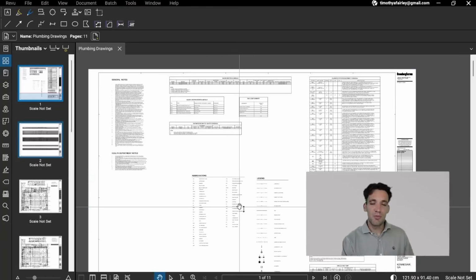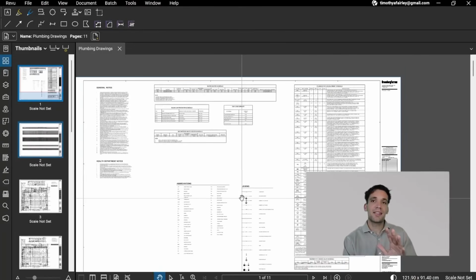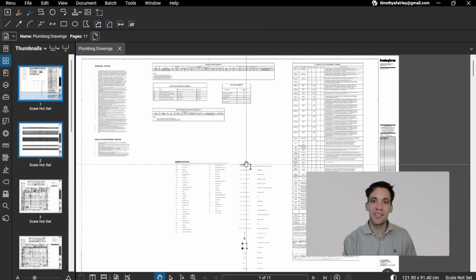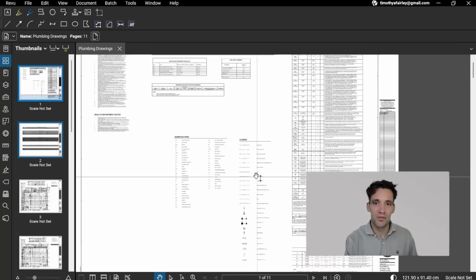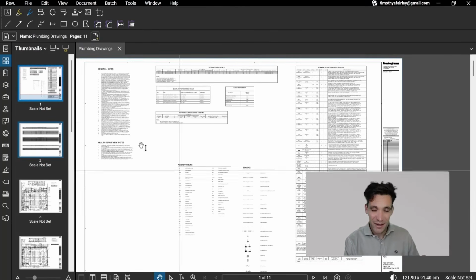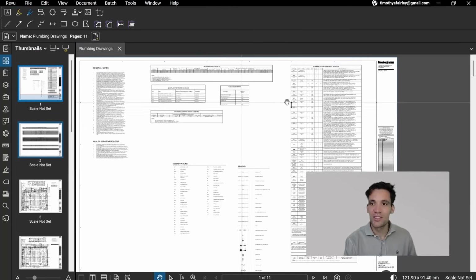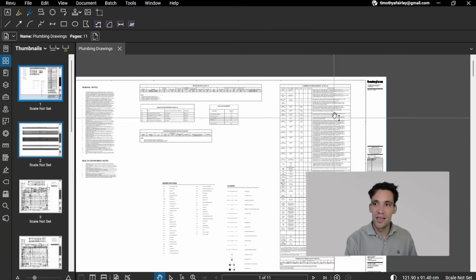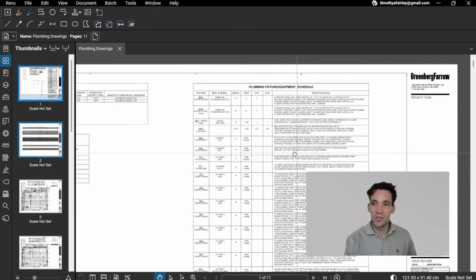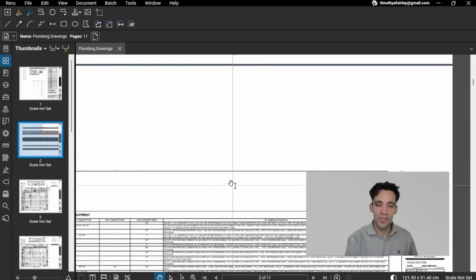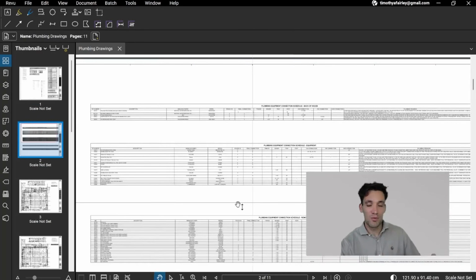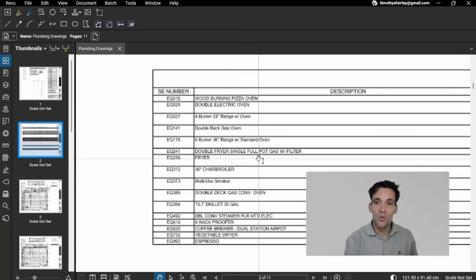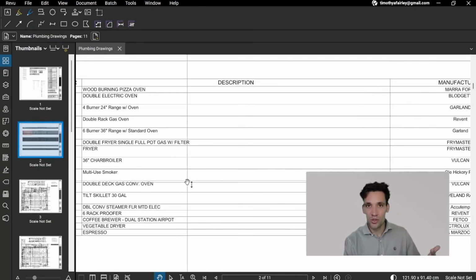Okay, so the next part of the plumbing takeoff is to actually understand the drawings. So we understand roughly what the system is. Now we have to look at the drawings to see how this system is built on our specific project. It's really only a handful of different types of drawings. We have general notes or cover pages within which we will have schedules and explainers of all these different systems. Our schedules, again, might be on the general notes page, might be on separate drawings, will give us almost all of our counts if the drawings do have schedules.